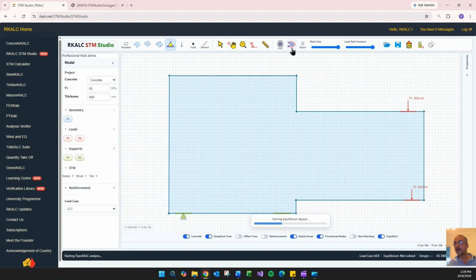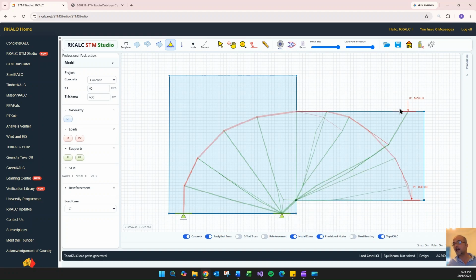So by clicking on this Mitchell truss, you will see what is the possible or the most optimum load path, which is making sense. You've got tension there at the back, and you've got compression goes there. So that is an X kind of arrangement. And you can have here tension here at the back, and you have a tie at this location. I'll have a normal model of X and X arrangement for starters. So this is what I'm gonna do.